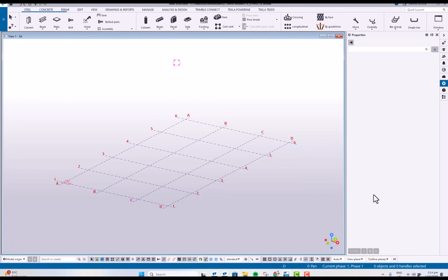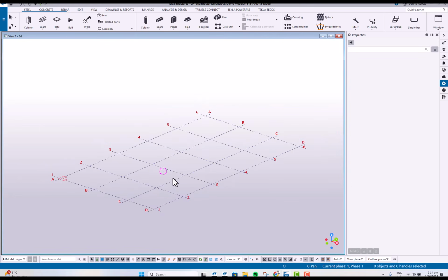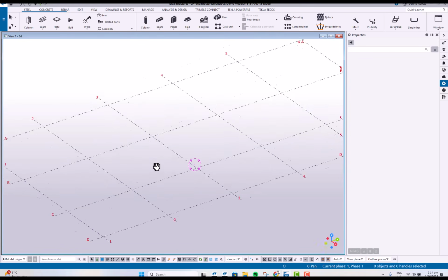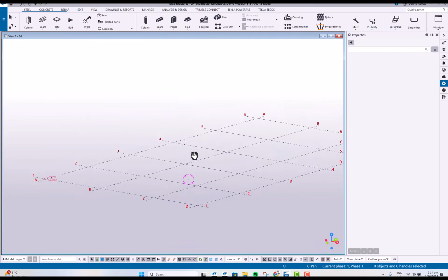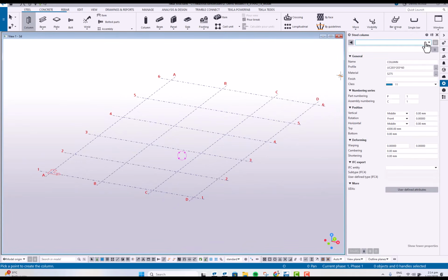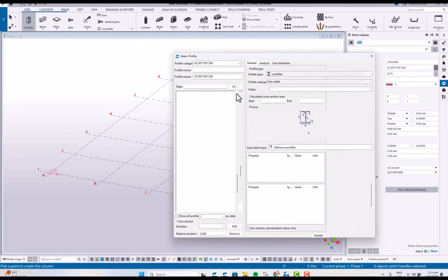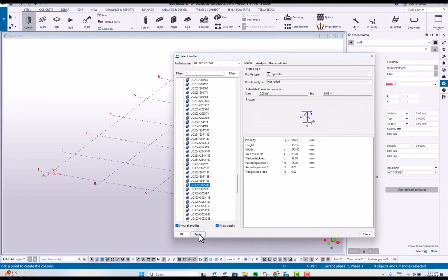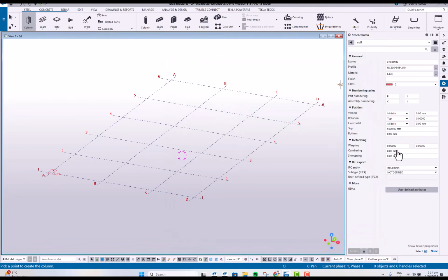And yeah, to start with this demo, as you can see, this is TEKLA Structures. This is a 3D modeling software and detailing software. So as you can see, you can rotate, zoom in, zoom out, pan. And I will start doing the modeling here. Here I have the steel elements that I can use to model, let's say, first is column. So I have the profile here. The profile is available in our library, which is a rich library of profiles from different environments. At the moment, we're using the UK environment.